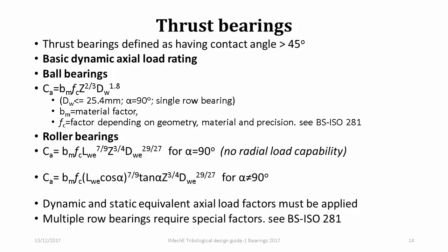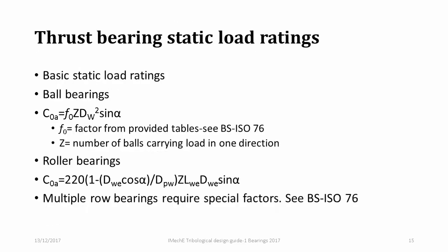Thrust bearing will of course have static load ratings. The basic static load rating for ball bearings is C suffix 0A, with an F0 factor from, again, tables in BS ISO 76.